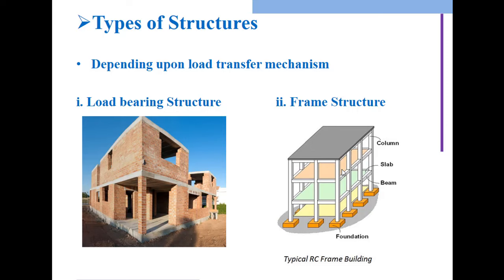Okay, now let's come to the brick. I'm considering two different components, like ballast and common burnt. If it is ballast, your weight will be 6.85 to 14.30 kilonewton per meter cube. Whenever I assign the brickwork over here, I need to confirm the weight I assign for the overall wall. If you take the wall over here having a height of 3 meter, how much load you are going to assign, you need to calculate.